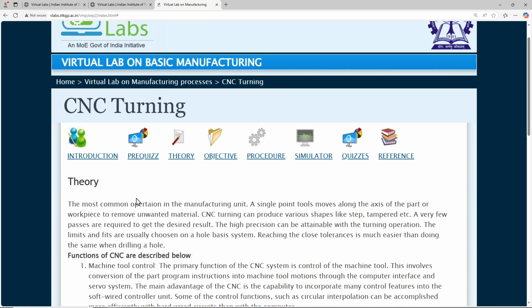The only point is the coding has to be there, the G code has to be there. Additive manufacturing is an alternative which gives us versatility; if there is complexity in the design of the component, that is more readily produced in additive manufacturing. But for mass production, producing maybe hundreds or thousands of components on a single machine in a single day, CNC machines are still being relied upon.